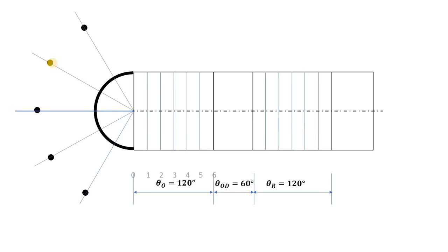Now draw the lines passing through this. Then mark these 1, 2, 3, 4, 5 and 6. Draw the horizontal line from this one till it intersects this vertical line from 1 at this particular point. Similarly, draw a horizontal line from 2 till it intersects this vertical line from 2 at this particular point. Same procedure we have to follow for the line from 3 till it intersects this vertical line from 3, and so on.